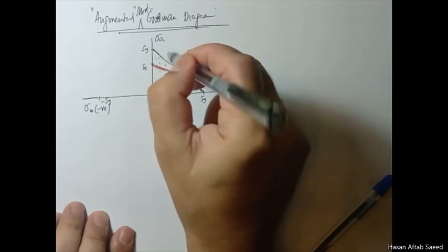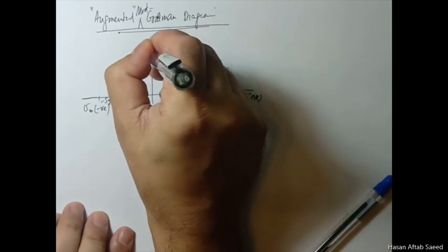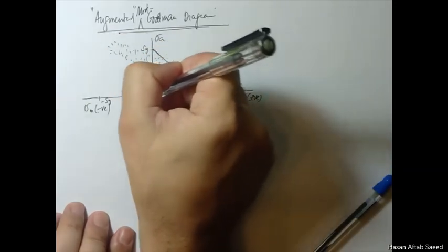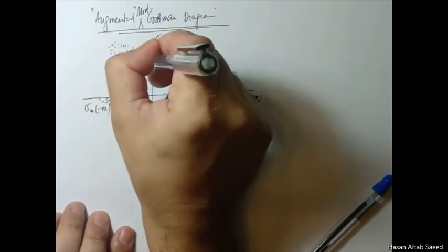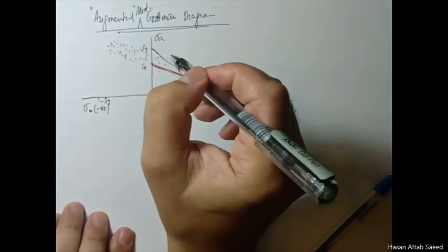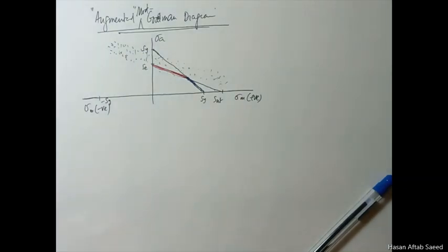But if your sigma m goes to the negative side, then actually, fatigue strength is increased slightly. As sigma m increases on the negative side, you can apply more value of sigma a for infinite life, and that makes sense. Crack propagation, basically fatigue ultimately causes cracks, and then they become bigger and bigger, and finally it breaks.